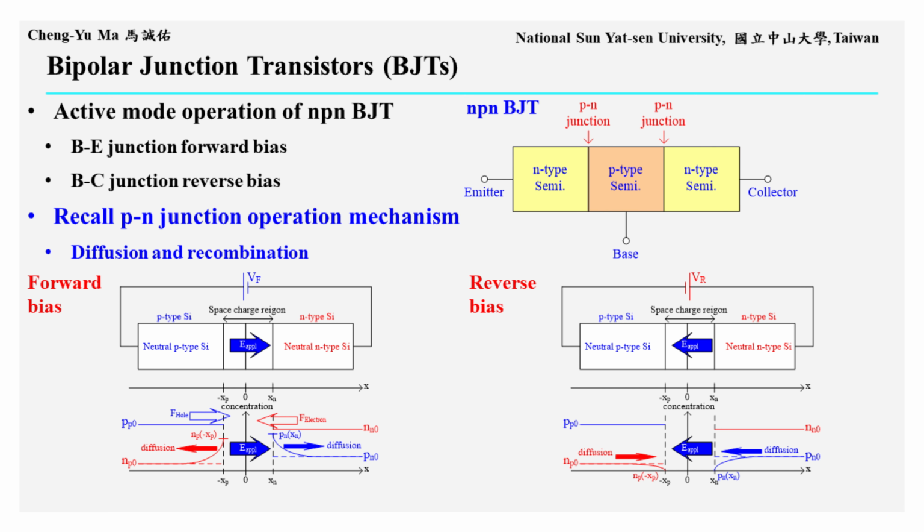When a PN junction is reverse biased, the minority carrier concentration near the edge of the depletion region decreases exponentially because of the reverse bias electric field. The minority carriers in the neutral regions still create a diffusion current due to the concentration gradient, but this current is very small, usually below 1 picoampere. Therefore, under reverse bias, a PN junction is considered non-conducting, and its equivalent circuit is an open circuit.